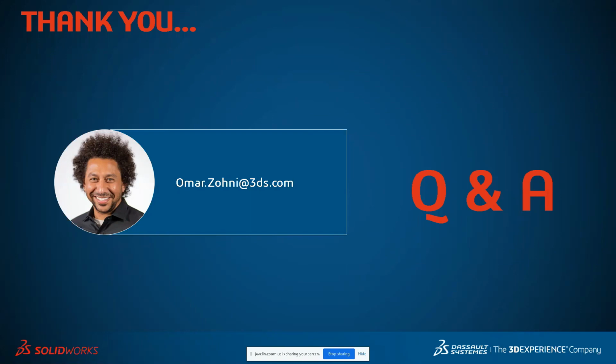Can you solve multiple studies simultaneously? That is a good question, and I don't believe you can. You can set them up to run batch. Well, I take that back. If you're utilizing cloud compute credits, yes, you can, because that's a non-interactive session. You can submit something to solve, close that out, and it's going to be solving on the cloud. You can go work on another thing, start that one solving, and submit that on the cloud. But if you're running it interactively locally, then you can't, although you can set it up as a batch so that it will run multiple solves. So if you want to run multiple solves, you've got to utilize cloud compute credits and non-interactive running. You've really got to run on the cloud.